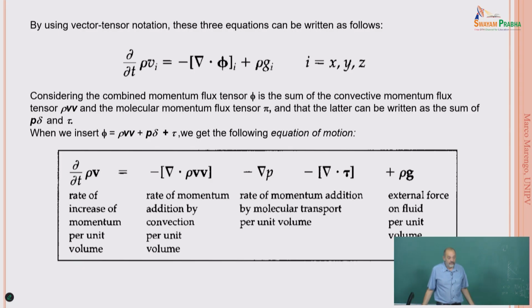And of course, we have the viscous forces, the viscous shear stresses, plus eventually an external force. The external force here is only G. Again, if we have a ferrofluid, a liquid, and so on, the external force can be something also completely different. It can be an electrostatic force, electromagnetic force. So any force that is acting on the bulk of the fluid. If the fluid contains, for example, magnetic nanoparticles, and we are putting the fluid in a field, this will be for us an external force. There are a lot of papers dealing with different fluids like that and so on.